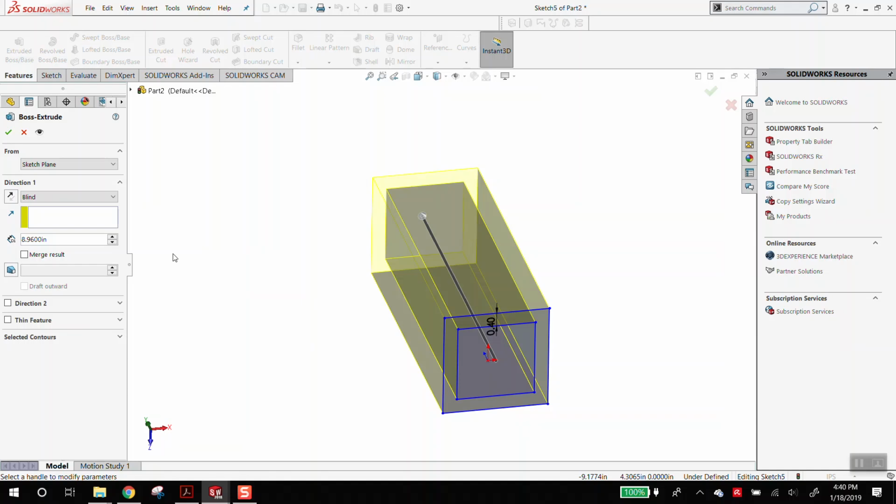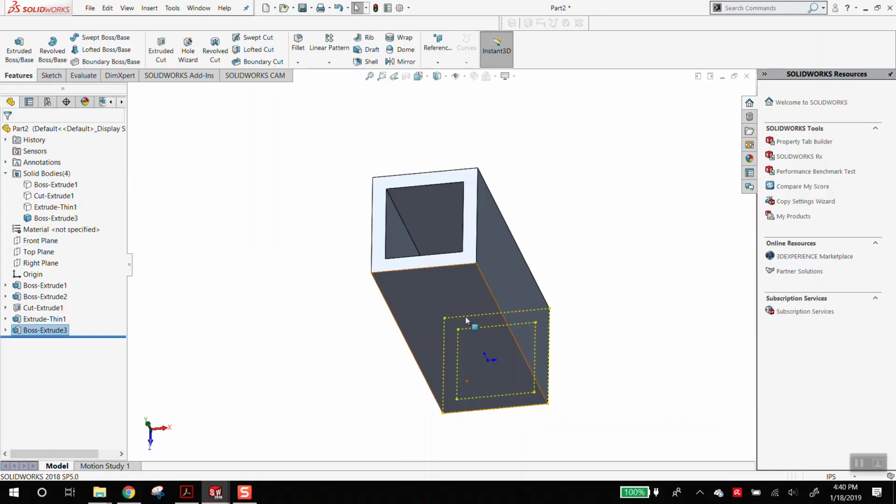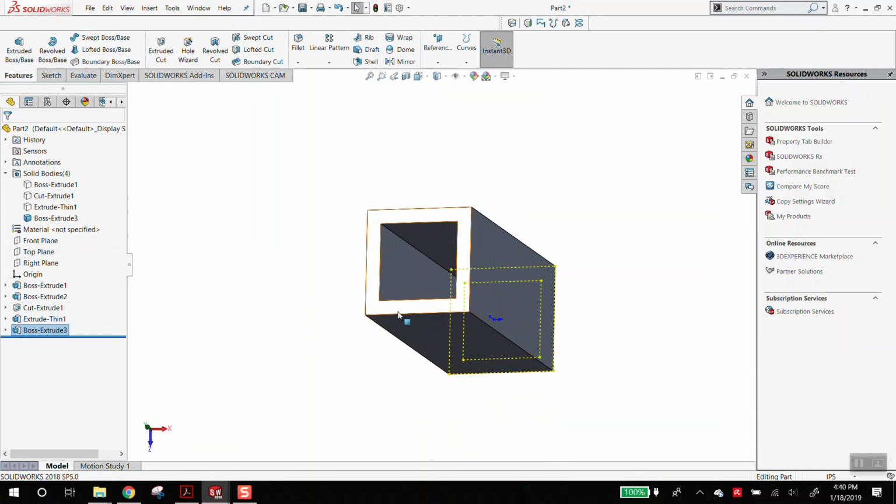Let's say you're trying to do this, what I would recommend. If you're doing a thin feature like this, I would do it as a sketch. That's just my gut default. There are other things like fillets that you could do as a sketch, but you don't want to do as a sketch. This is the best way I can verbalize it. I think it is just more typical. Doing an extrude as a thin feature is somewhat not typical, at least in my experience. And that's my main answer.